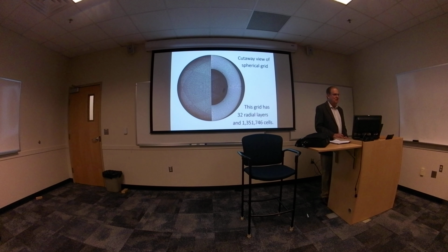It's possible to impose symmetry and just do, say, half the problem to save computer time, but you limit the realism when you do that. So yes, you can do that. If you want to get just a first idea of how the system's going to behave, you can impose symmetry that may not exist in the problem you're interested in.